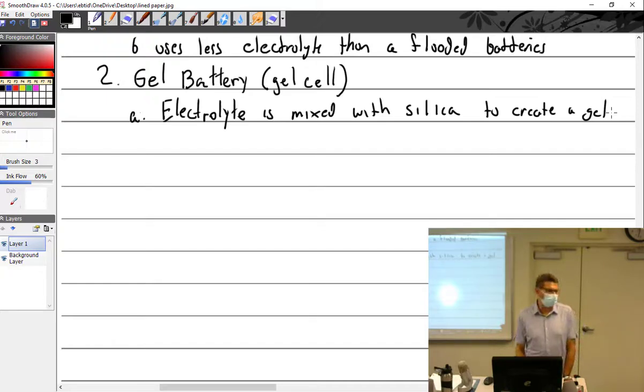So yes, if you have a high silica content in your oil analysis, you have a problem with your induction system. You have leaks, and you're getting silica in.